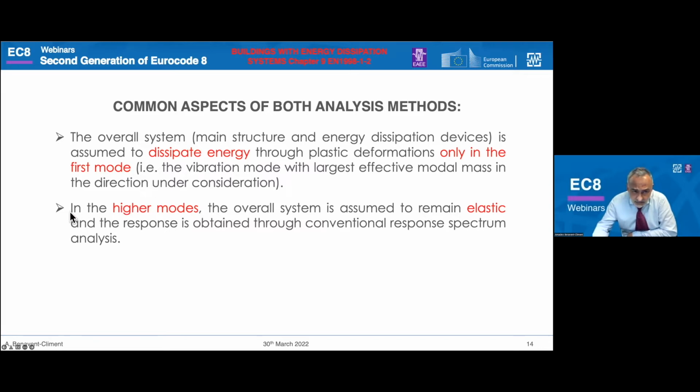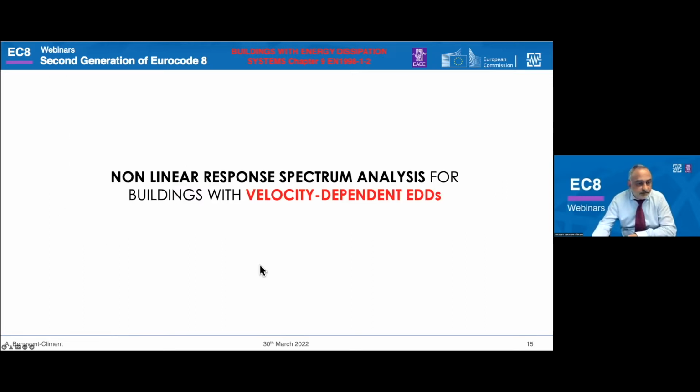And second, in the higher modes, the overall system is assumed to remain elastic, and the response is obtained through conventional response spectrum analysis.